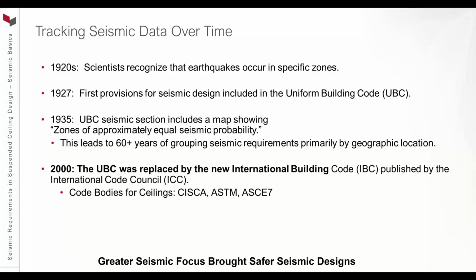And so we've tracked data, and what happens is we don't just want to design for the quake itself. We want to design also for the secondary aftermath of the quake. So the earthquake can hit, but what happens is it causes more devastation if things in the building are not put together correctly or seismically braced or supported in the way it needs to be. So some of the secondary events or effects could be something moving in the building, causing a utility to come disengaged from where it's at, fall down to the ground, causing more destruction.